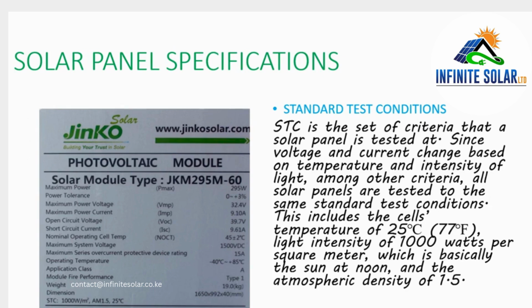Among the panel specifications we are going to look at are the maximum power, Pmax, power tolerance, maximum power voltage, maximum power current, open circuit voltage, that is what is indicated as VOC, short circuit current, ISC, and nominal operating cell temperature.